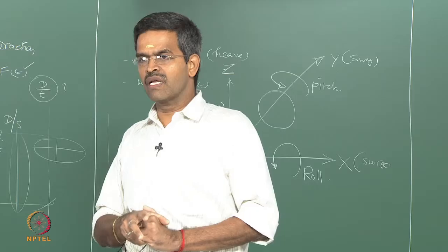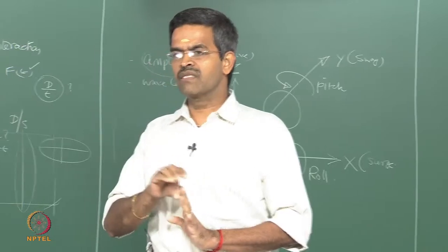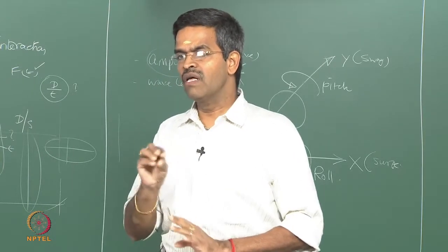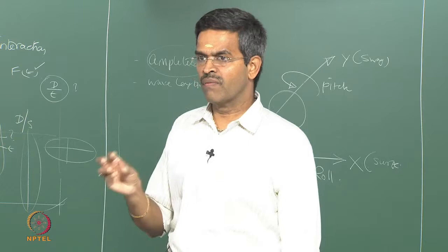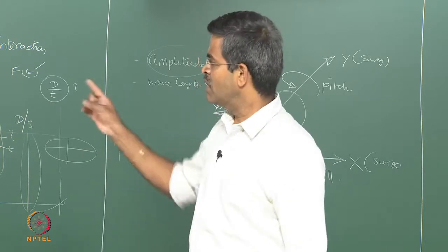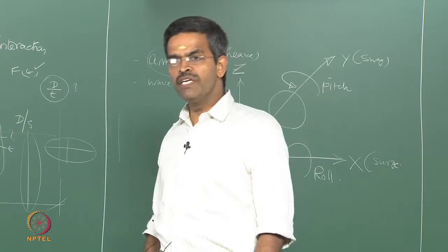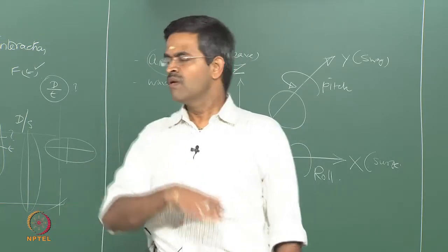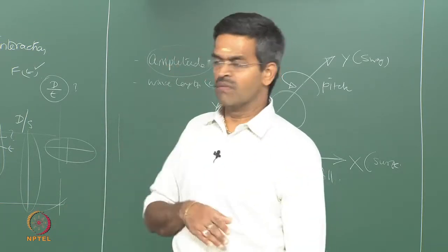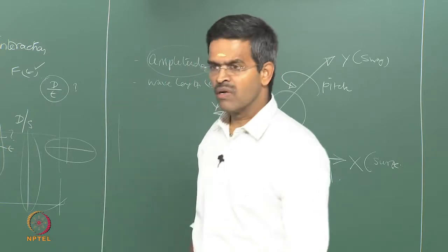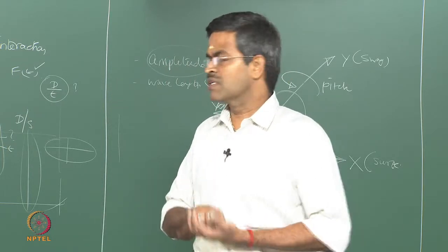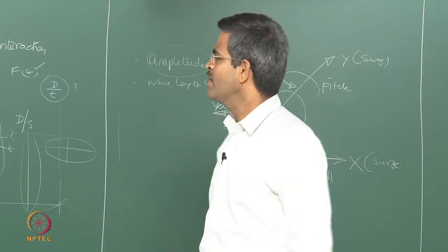Because added mass is an acceleration term which comes from the additional acceleration component arising from the oscillation of the body given in the 6 degrees of freedom. Therefore, added mass. Why damping coefficient? Because this will induce a damping force on the water around the vicinity of the member, therefore damping coefficients. Now, they all will come into play in all 6 degrees of freedom, resolved accordingly.